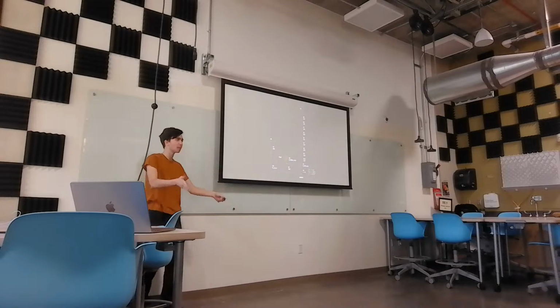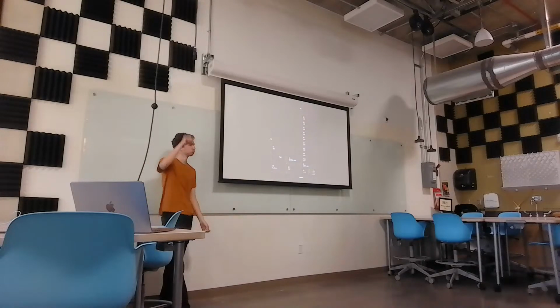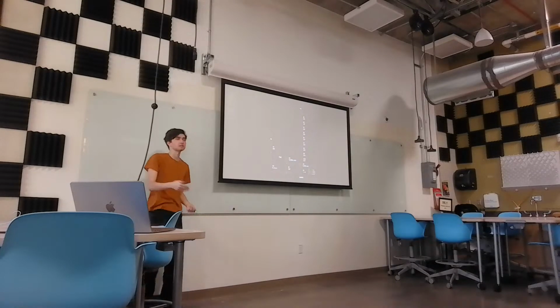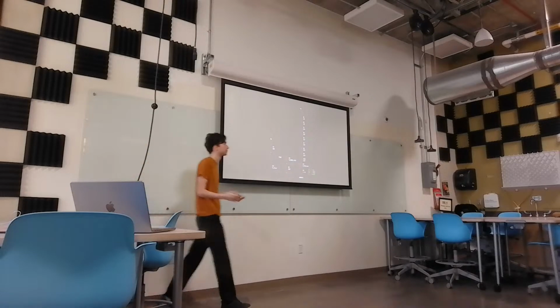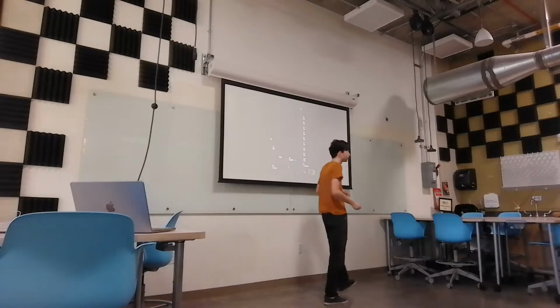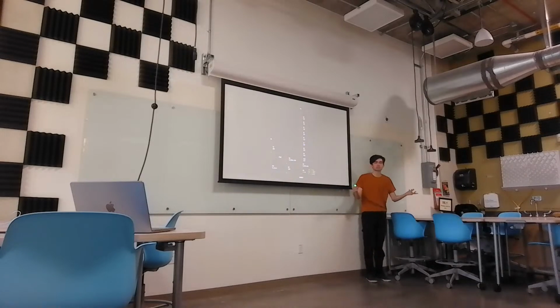It's a huge amount of current flowing through them. So I just put them in series: super high forward voltage, very little current. Adding more LEDs does not increase the current. They're in series, so the current goes through all of them no matter what. In this case, I have 9 really nice 6-volt LED modules, which is a forward voltage of 54 volts. So as long as my battery voltage is more than 54, we can turn it on.